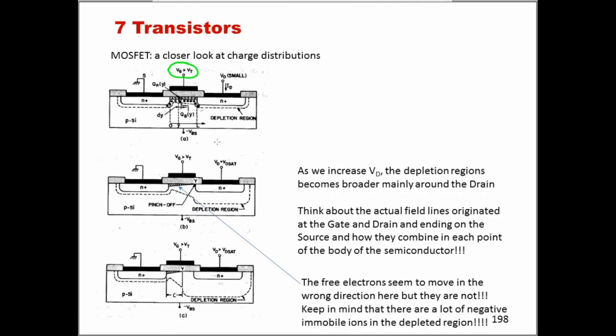So if we go back to our transistor, when we apply a certain gate voltage and VD is very small, then we could say that we have our inversion layer here, and this dashed line is indicating the extent of the depletion region. So here we have our P carriers, and between the solid line and the dashed line we have a depletion region. When VD is very small, both on the source side and on the drain side, more or less the same thing is happening.